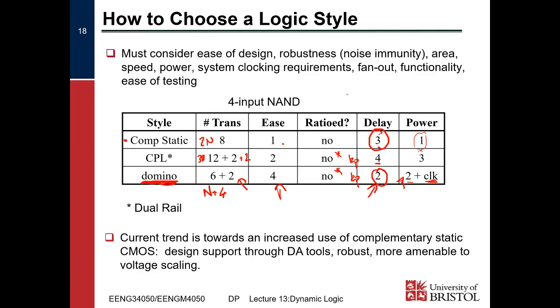So what we generally tend to find is that CPL tends to be used for either FPGAs or semi-custom ASIC designs, right? For FPGAs, having that inverted version of the signal, or another one is CPLDs, are also quite common for this. Having that inverted version of the signal is very helpful because you don't know whether your circuit's going to be inverted or not.